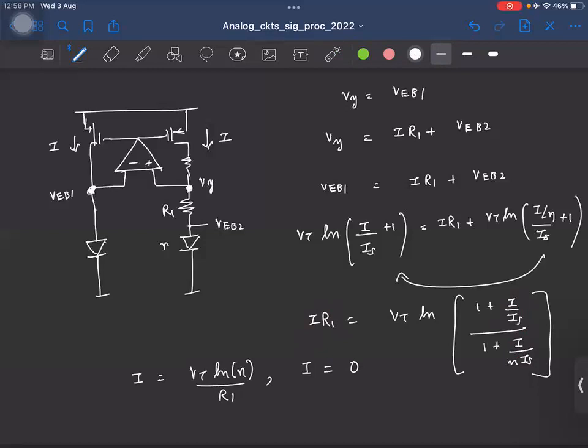If you have a linear set of equations, you can have either one solution or infinitely many solutions, right? Basically, two lines intersect at one point, or are exactly parallel. If you have a nonlinear set of equations like this, you can have two solutions, right? So you shouldn't be surprised if we have multiple solutions for these kind of nonlinear circuits. And this is the required solution, but you also see we have one other possible solution. And it is an equally valid solution, right?